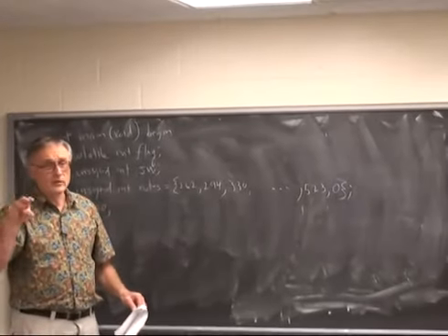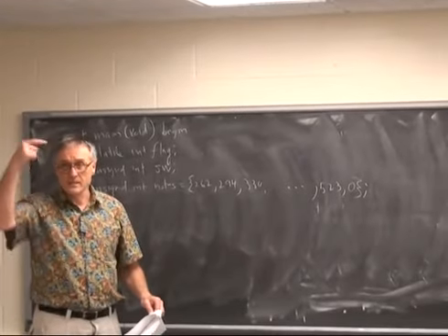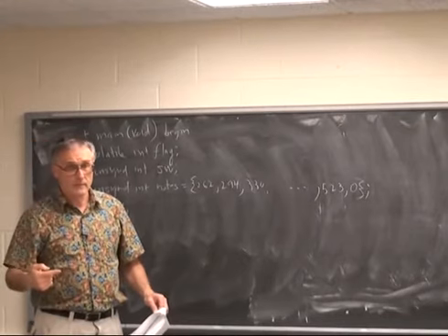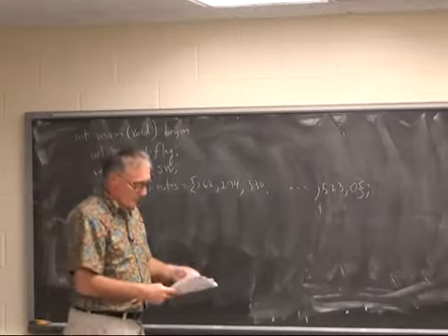This is a down counter. So it starts at the loaded value, counts to 0, throws an interrupt, resets itself since I've specified continuous mode, and starts again. The usual periodic timer.